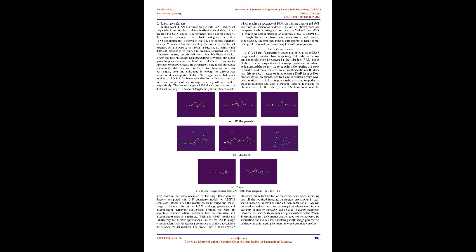The simulated ISAR images are obtained as follows. Create an HFSS project in the ANSYS Electromagnetics SBR+ solver and import the 3D model of the ship in the workspace. Assign the material of the ship as PEC and change the units to meters. The orientation of the ship along the x-axis, y-axis, and z-axis should be ship length, height, and width, respectively. This is because the radar is placed in the XY plane at an angle, the look angle, with respect to the x-axis as per RADAR pre.